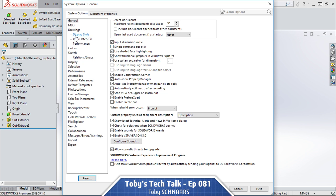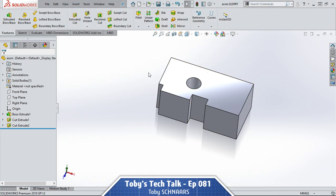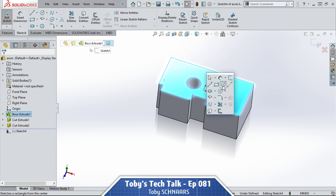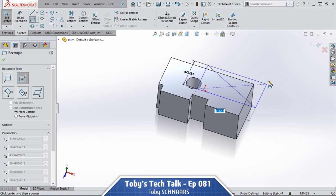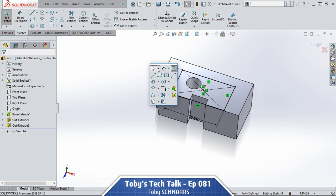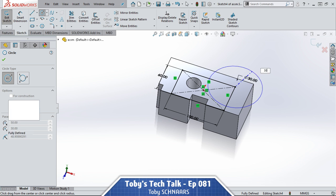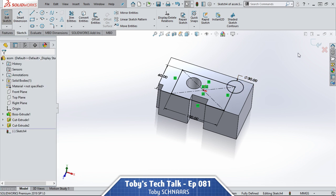Next, I go to options here. And when I go to options, I'm going to go to sketch, and I'm going to go to enable on-screen numeric input and create dimension only when value is entered. What this is going to do is it's going to give me the auto dimension functionality that I love. So 60 by 100, and I immediately have that rectangle defined. Or I could draw in a circle here, and when I go to draw this circle, I could type in a value of 30. So that's that auto dimension in sketch mode, definitely like that.